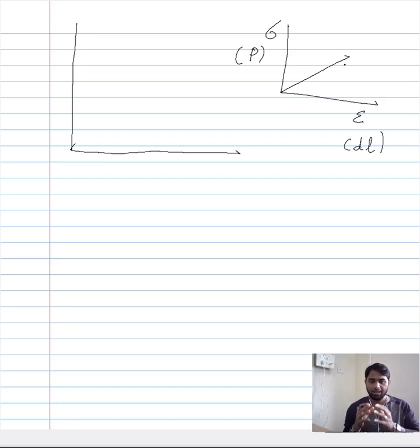But since creep adds an additional degree of freedom, meaning in creep you have to consider time as well, in addition to your stress and your strain you have to include time. The very definition of creep involves time. You cannot get rid of time, it is indispensable. Time is the characteristic feature that defines creep, so you have to have it in your graphical representation. So time will assume the x-axis, and we have two other parameters to select from.